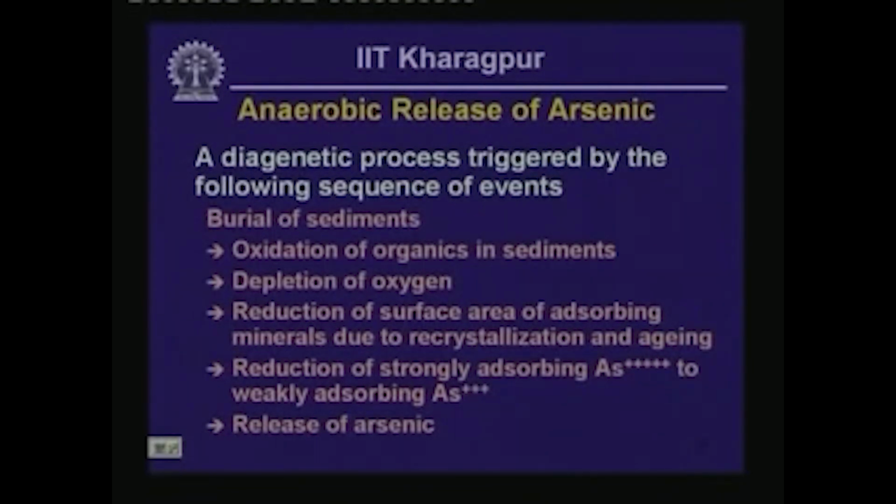Reduction also changes pentavalent arsenic that naturally occurs within the sediment to trivalent arsenic, and trivalent arsenic is weakly absorbing in comparison with pentavalent arsenic, and that leads to release of arsenic in groundwater.